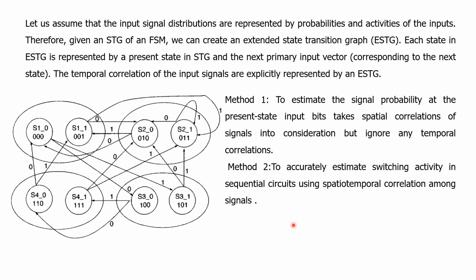So based on this, signal probability, signal activity, state transition probability, transition switching density, everything has to be calculated. If the input changes from 0 to 1, there is a transition. At the same time, depending upon the input slope, if the input is changing from 0 to 1 at different nanoseconds, 1, 2, 3, that is the rise time. Depending upon that, the power can be estimated.